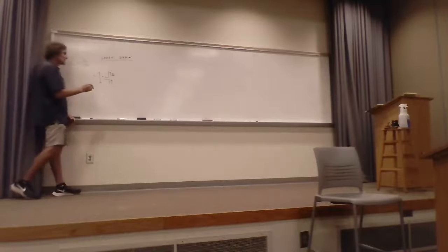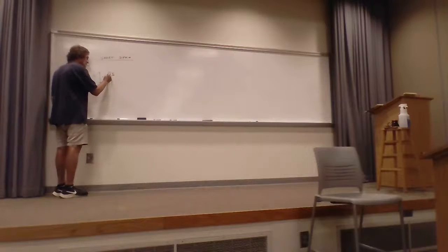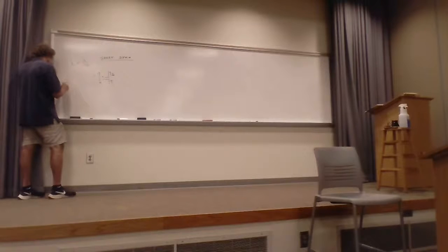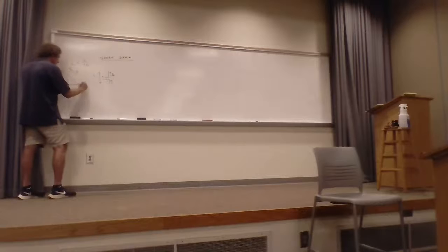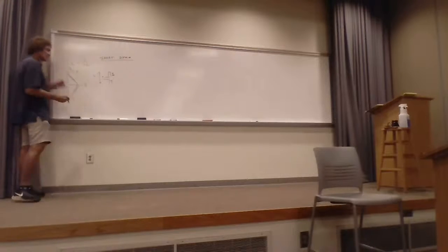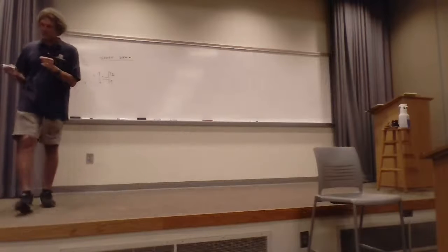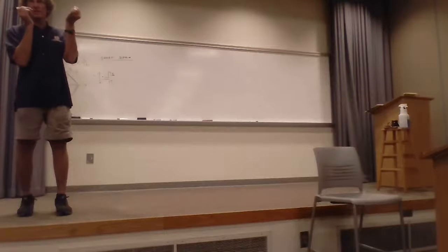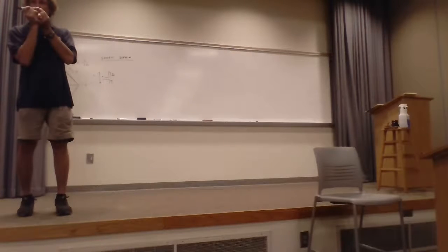I'm going to say that. See, he's assuming the current at this end is the same as the current right there. In reality, I'm just telling you this, your professor, if you plot the magnitude of the current in this direction versus position on the antenna, it would taper down to zero at the ends, and it has to. What does your common sense say? If current's flowing in, whatever's flowing in is staying there or leaving, right? Right at the end of the antenna, you can accumulate some charge, but overall, it doesn't go to zero.